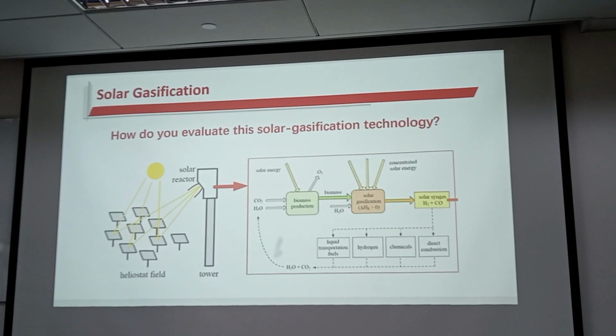But from the traditional gasification process, when we talk about downdraft gasifiers from the top to the bottom, actually the temperature increased gradually from room temperature to 200 degrees centigrade to 600 degrees centigrade. But if this technology is used in this process, I'm thinking how to control the temperature on the top. Does it change the principle of gasification? It may be possible, but we should talk with researchers. How does he think about that?